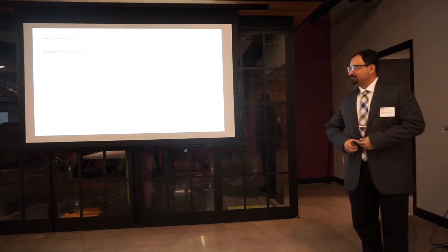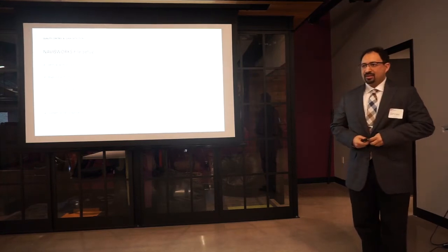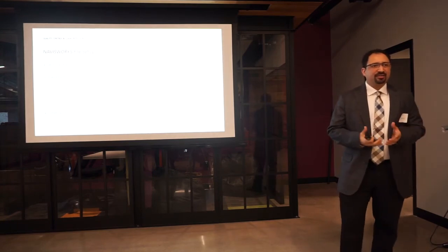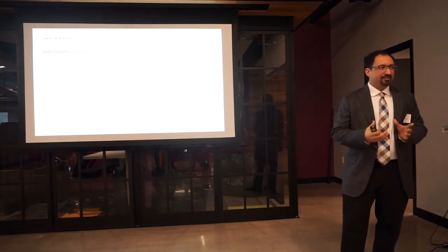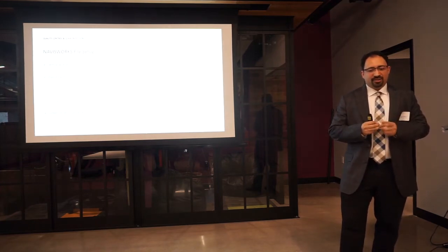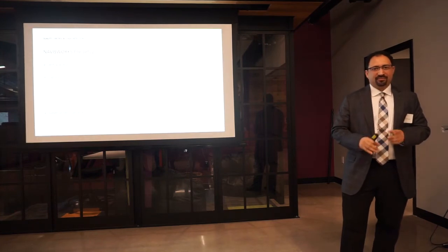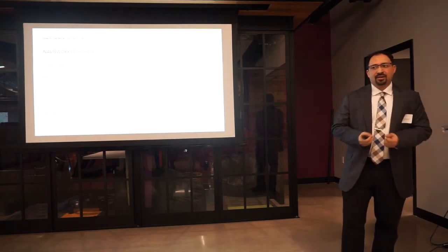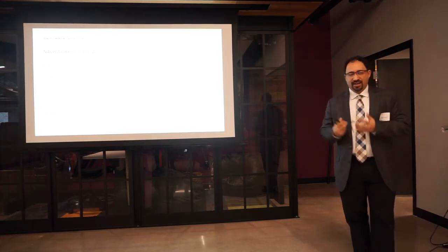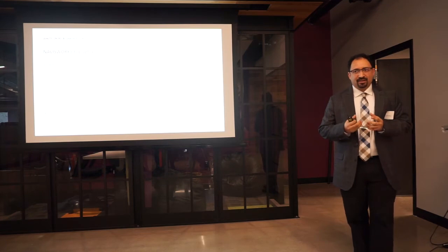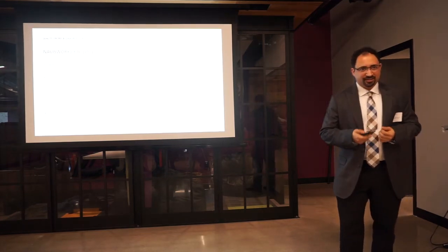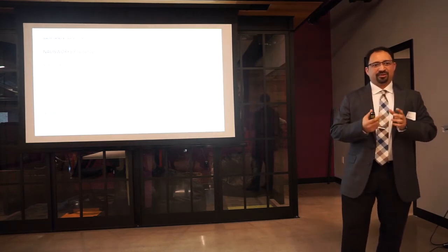So, just to talk a little bit about Navisworks, in order to set up a Navisworks file, these files are huge files, considering that every single file is linked into the architectural file at the moment. We had to pretty much clear out every unnecessary item in the file, remove all sheets from the file, and leave it as one big 3D view, and bring it into Navisworks. It was probably about a day's worth of work just to create the clash detection, just because of every single bend in the pipes in this project.